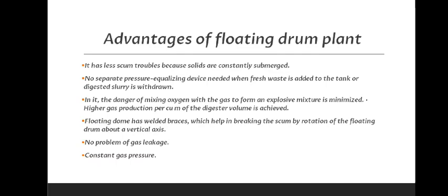Higher gas production per meter of the digester volume is achieved. Floating drum has welded braces which help in breaking the scum by rotation of the floating drum about a vertical axis. No problem of gas leakage, constant gas pressure.